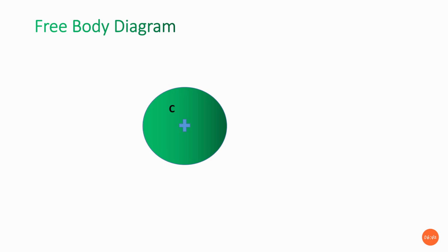So we are going to consider the free body diagram for that wheel. What is our first condition? We need to remove all the supports, the horizontal plane as well as the rectangular block. In this case the wheel is going to try to roll over the block, so we need to consider the reaction forces here. First I have taken the wheel and its center, and the weight acts vertically downward. At the same time I have taken the line of action.